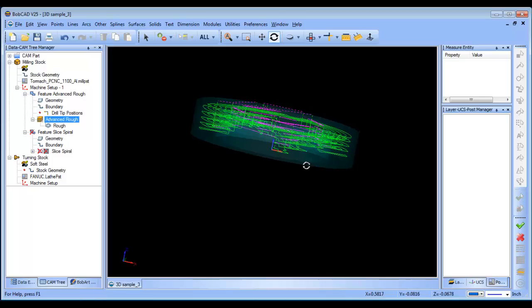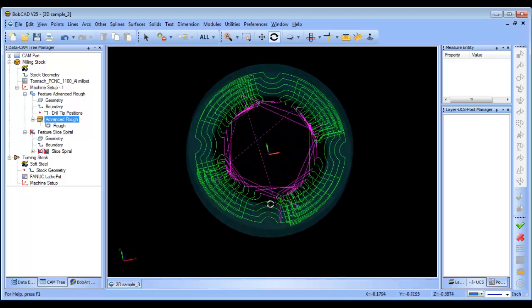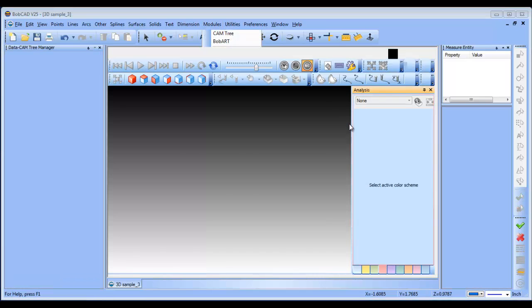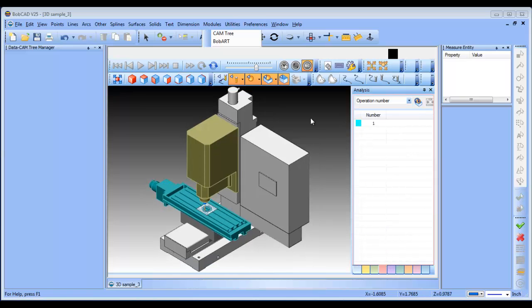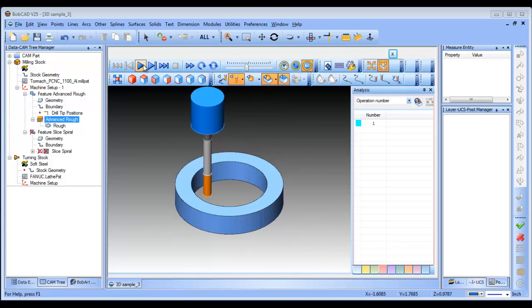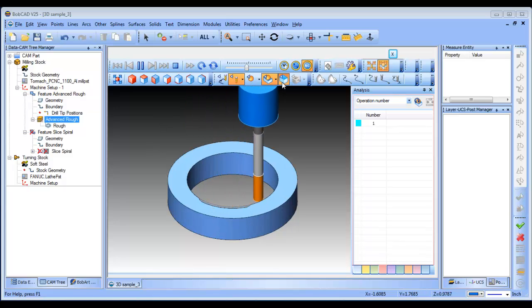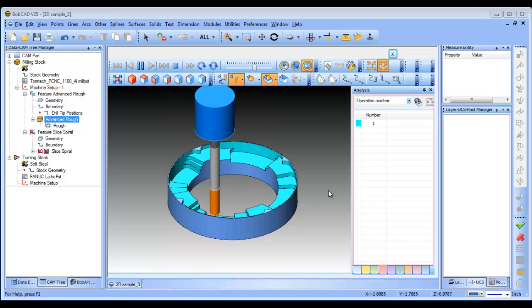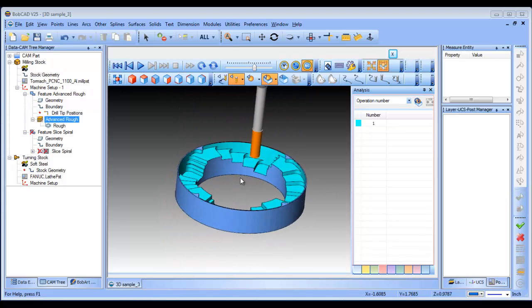But anyway, let's get back into our settings here. So we see this is our offset style toolpath. We're stepping down, stepping over. And when we run this through the simulation, really what we're doing is taking a shallow depth of cut and a shallow step over, and that allows us to come in and machine this part. So when we look at our ability to speed things up or to cut more efficiently, the next option really is the high-speed options, or what we call adaptive roughing, right?